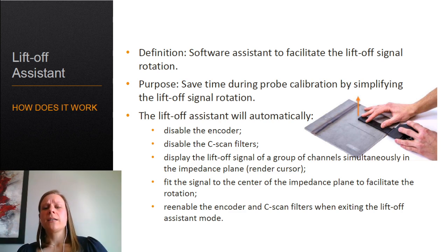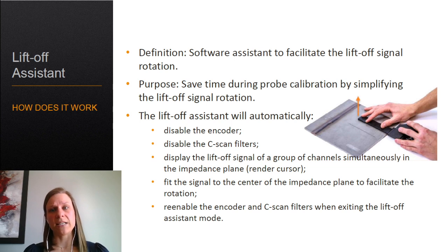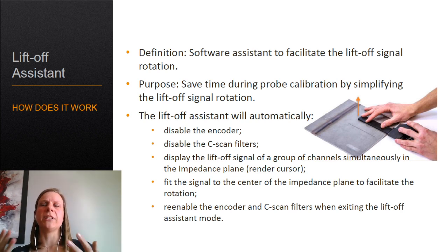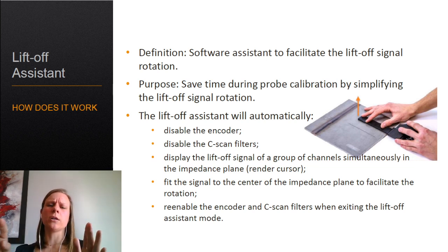So if I summarize quickly what I just mentioned in different aspects. So the Liftoff Assistant is a software assistant to facilitate, on the slide it's written the liftoff signal, but you could use any reference signal. You could rotate based on a signal coming from a notch, or you could rotate on the background noise. So if you have an application where the liftoff is very well controlled, but the material has some property changes inducing noise, you could also use that reference. So it's called the Liftoff Assistant, but it's basically a tool to help rotate the signal.